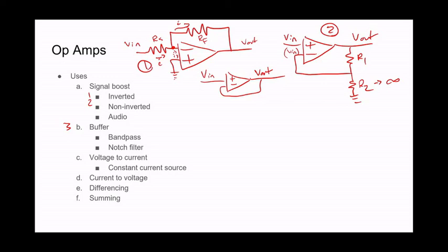Now the reason why you need a buffer here is, for a band pass filter, we're letting the band go through, which means you want to have a low pass and a high pass, or sorry, a high pass followed by a low pass. So I'm going to do a terrible example and just do a quick and dirty high pass followed by a low pass.